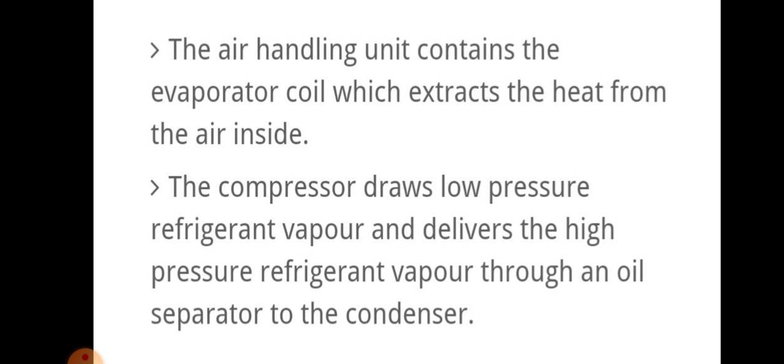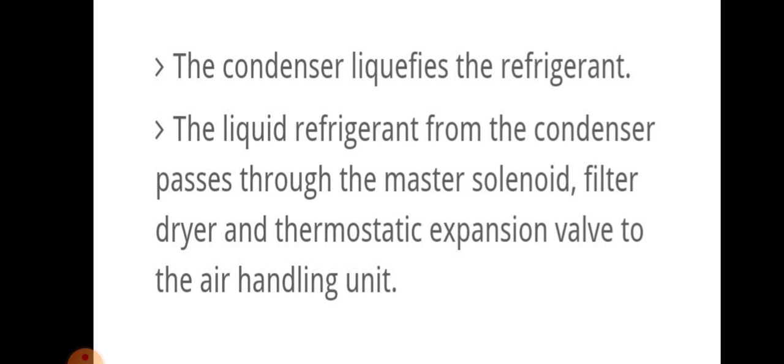to the condenser. The condenser liquefies the refrigerant, and the liquid refrigerant from the condenser passes through the master solenoid, filter dryer, and thermostatic expansion valve to the air handling unit.